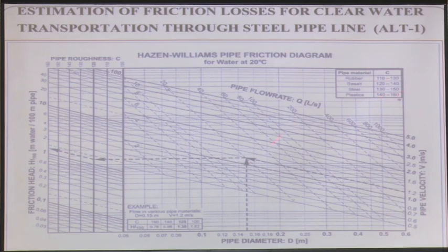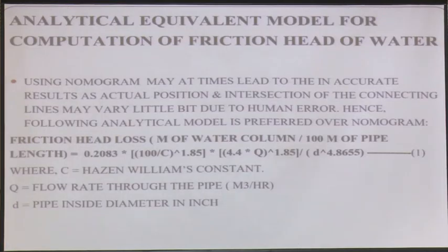So, probably he has considered this is rubber lined. So, if it is rubber lined, yes, 120, but normally when we do steel, then it is 140. If it is rubber lined, consider 120, right. Is this diagram clear? So, again the value whatever you get for friction head will be for the clear water.